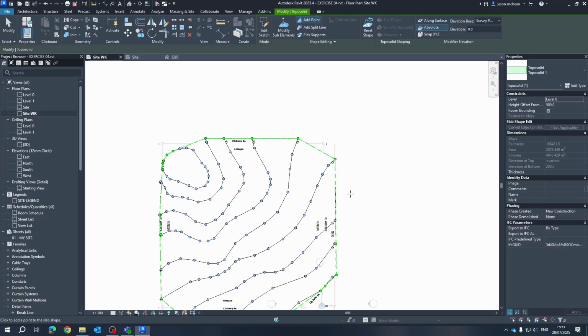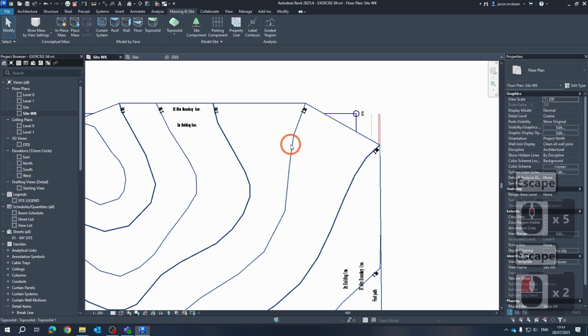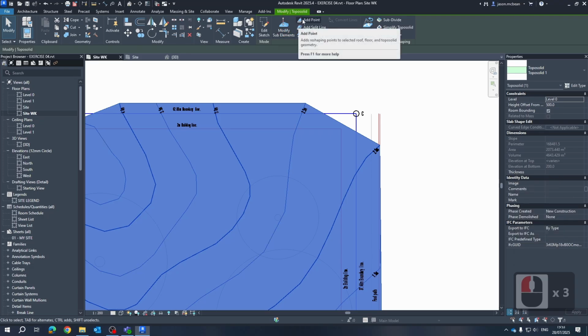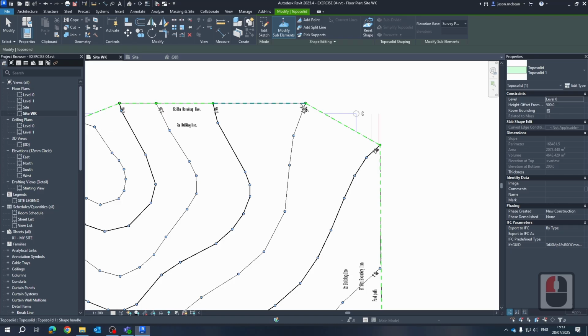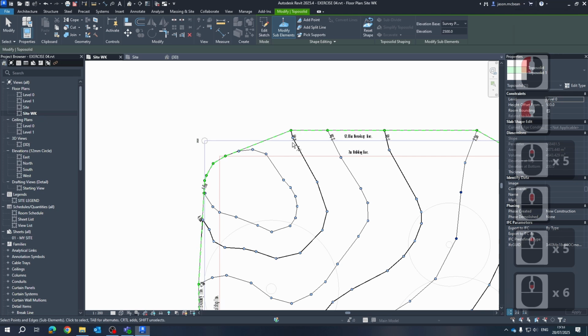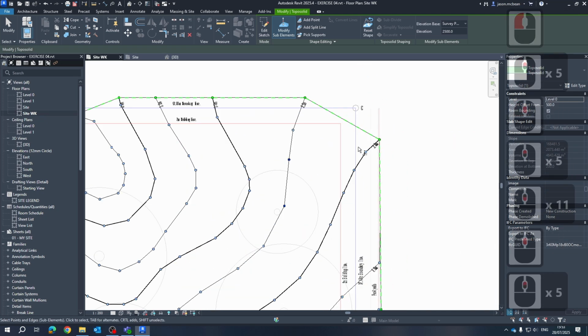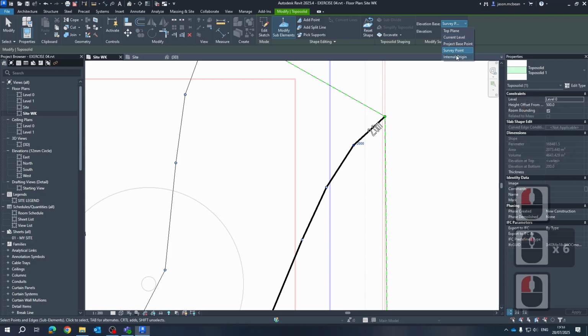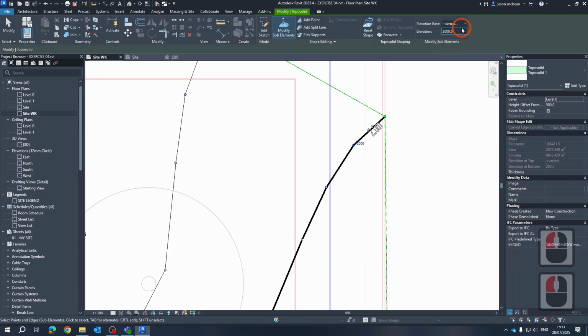And you can see if I select a point here, all that Revit has done is gone and looked at the DXF file that I've imported and linked in, and you see it's created a series of these points along the contour lines that it could find in the project file. So straight away, Revit's tried its best to create a site based on the information, and it's assigned the values. Just remember, you can designate different points, but for now we're just going to use survey point or internal origin. They're exactly the same point at this moment.